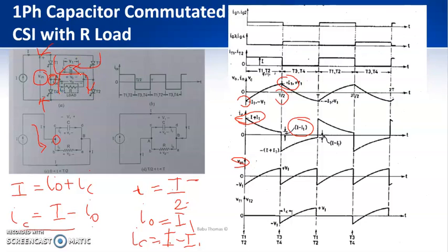So the voltage across the load will be changing polarities, which is visible from this particular figure. But the voltage Vin is not going to change. So we can plot the same schematic of voltage for Vin, which will be repeating at all time periods. So that is for the input voltage Vin.